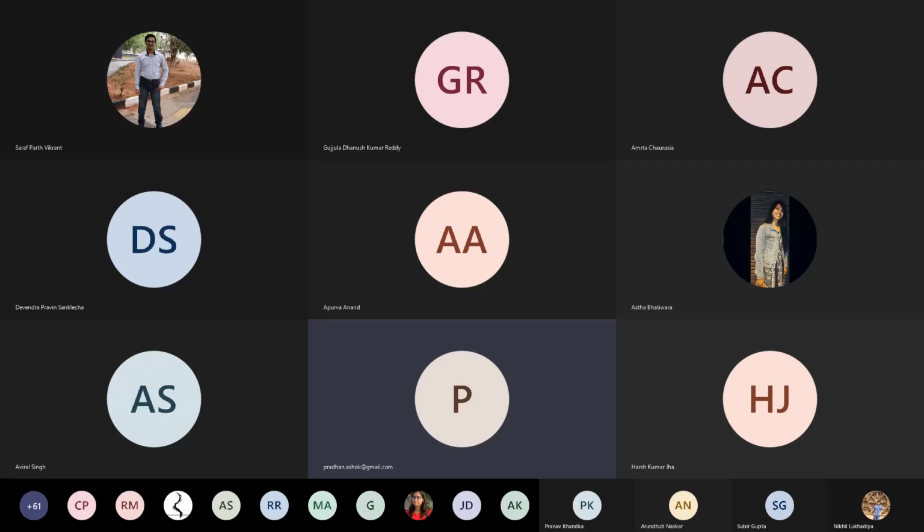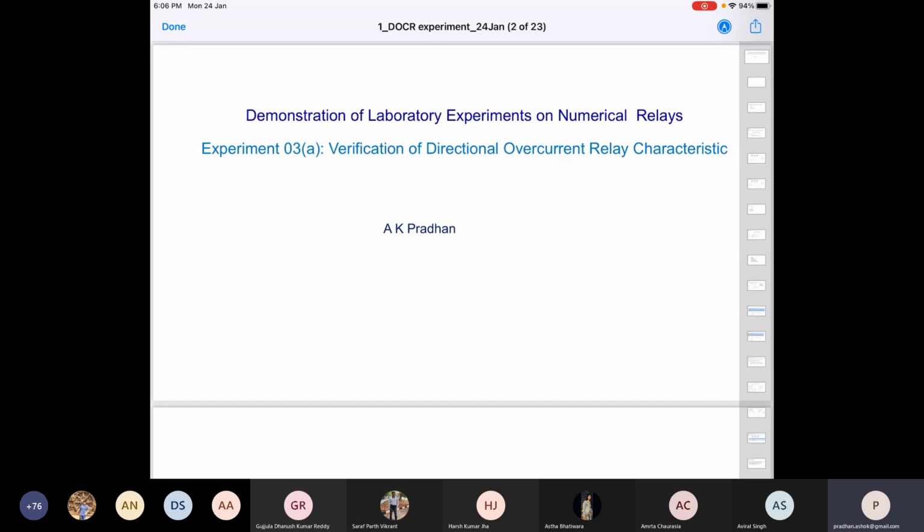perspective. So percentage bias differential relay has a specific characteristic, and you use that for transformer protection. And I told you that that is valid also for any other type of element protection, including distribution line, transmission line, reactor. So many other elements are also being protected by differential protection.